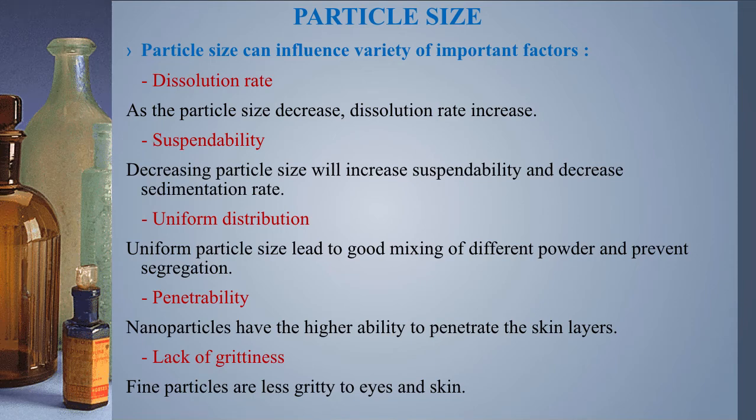Good morning, everyone. Our chapter today is about particle size analysis. First, we need to know why particle size is important. By reducing particle size, the solution rate will be more, because reducing particle size will increase surface area of contact between particle and the surrounding solution medium, so the solution rate will increase and also solubility will increase.